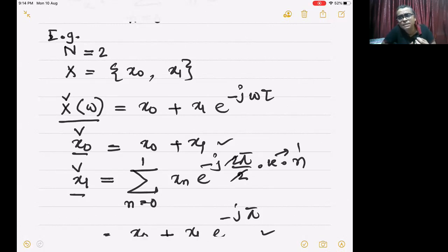Instead, we can take a discrete Fourier transform and store only the small frequency components which our eyes anyway can discern. Those very high frequency contents, very high contrast contents, our eyes may not even be able to distinguish between. So therefore, it always makes sense to do this kind of transform and send only that information that is required.